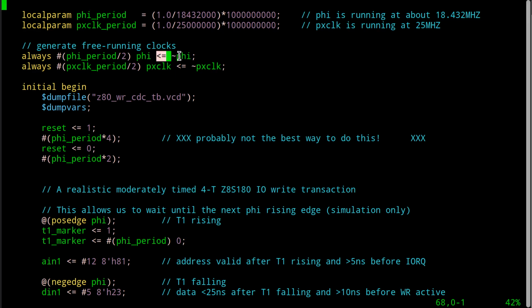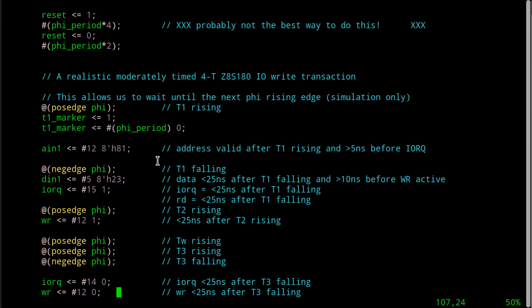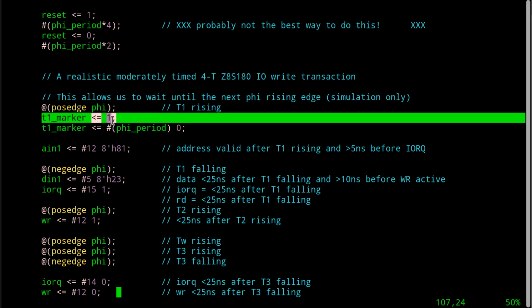If this is not something that's ringing yet, you may want to pause this, go back and listen. This is the whole core of this recording today, all right? You want to make sure that in your test bench this takes place as if it were inside of one of those always blocks in a sequential circuit type of design so that you go at the right time. If I did this with a non-blocking assignment and I just put a delay in here, then this value could change in that time period, but before somebody consumes it.